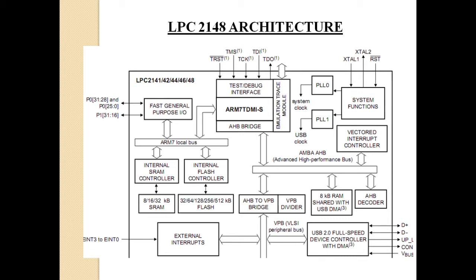Why is it not accurate? Because so many passive components are used for generating the clock. For making the astable multivibrator, you need to connect some resistors, some capacitors, etc. to the 555. All these passive components will have their own tolerance, so the clock output will be slightly varied. It will not be accurate, so you cannot use that.